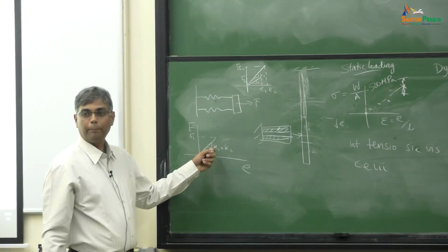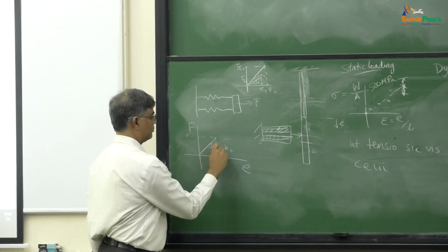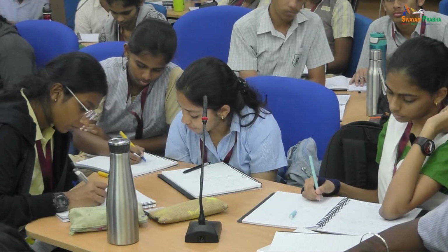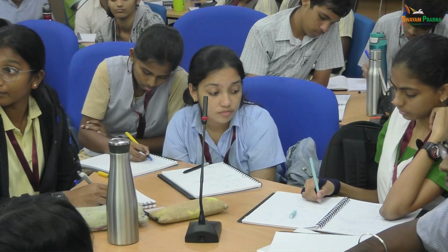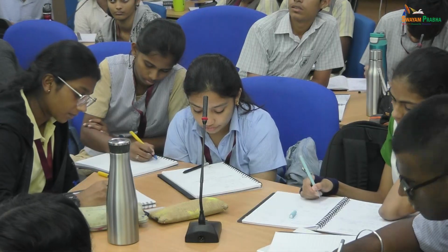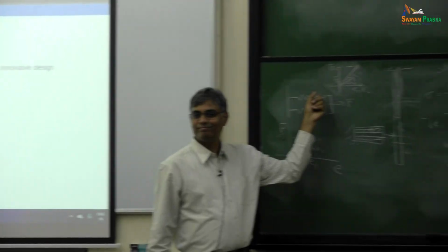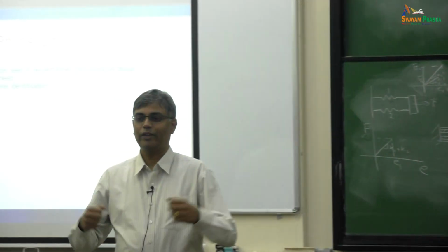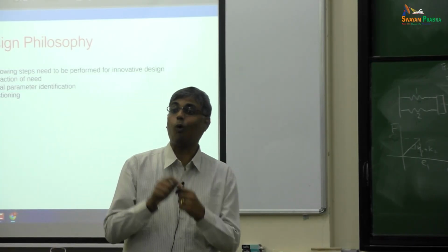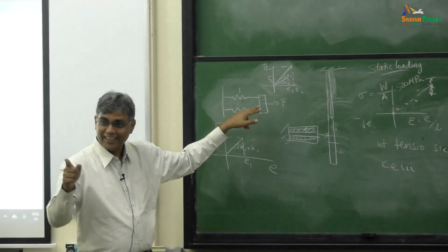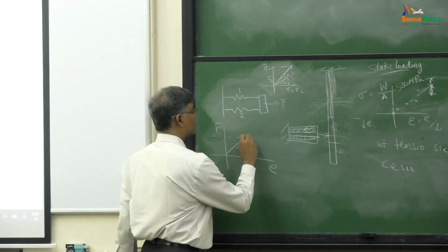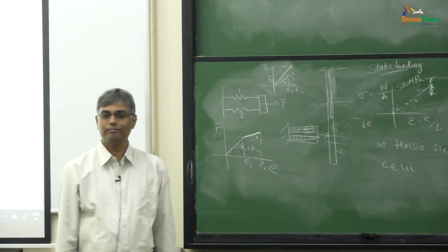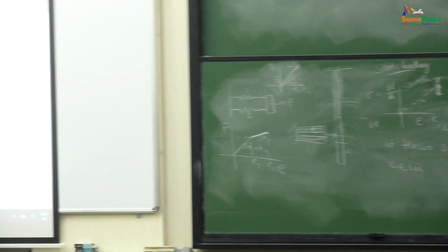Okay. So what will happen is, up to the point where both springs are extended to E1, both springs will be resisting the load and the modulus will be K1 plus K2, right? Then at that point, suddenly this one will break. I don't know which one is one, let us say this is 1 and 2, so one will break. Then if I continue to load it, it will reach E2, but at what slope? Now K1 is gone, it will only be K2. So suddenly the slope will change and it will go up to E2, and then even that will break.